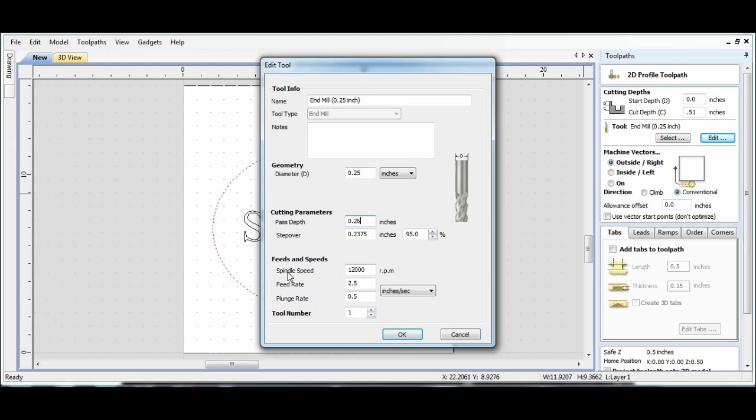Spindle speed is another thing that you can ignore forever on this machine. Some CNC machines can actually read the spindle speed that you want, and it will change the spindle speed to whatever you want. Our machine does not do that. It is not that smart. It actually has 5 or 6 manual adjustments directly on the router that changes the spindle speed. So you can change this to whatever you want. It does not matter. And once again, that is just on our machine. If you go to a nicer, more expensive machine, you will be able to dial this in a little bit better.